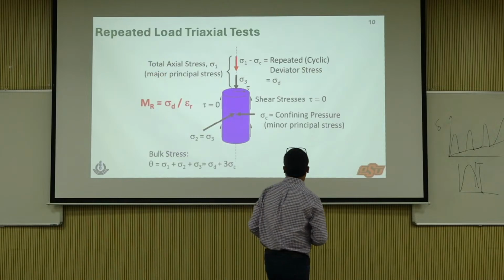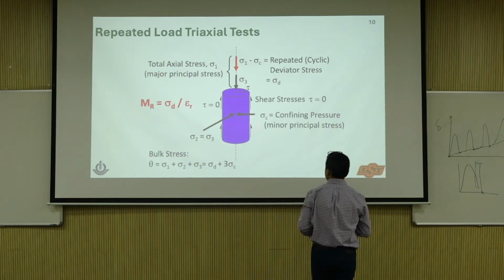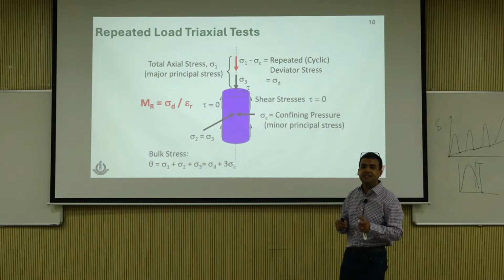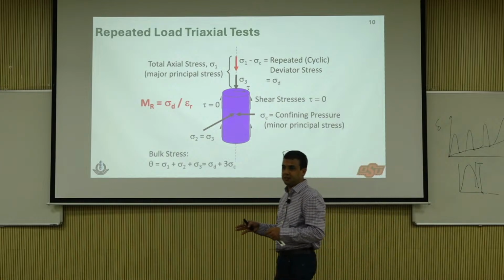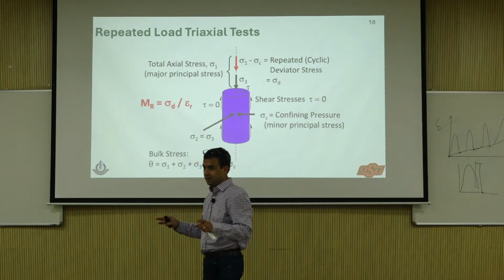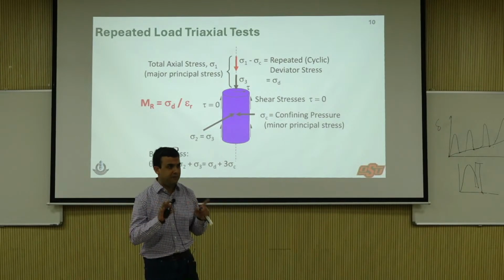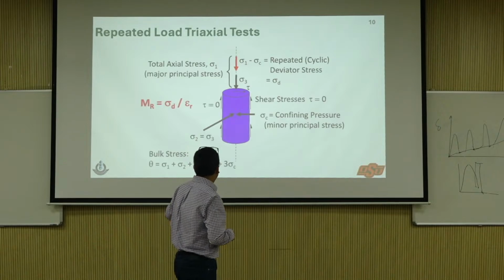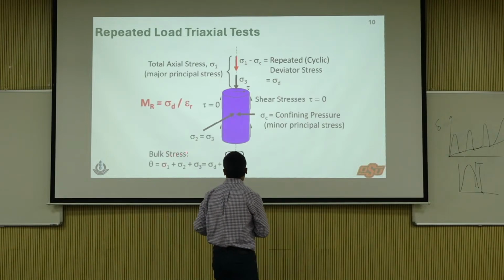So that's what triaxial testing typically does. We talked about this a little bit. There is no shear on the boundaries, and that is the reason we are able to fit principal stresses. Otherwise, it's not true. So be very, very sure about this. Okay. Then there are some other things that we are going to define.